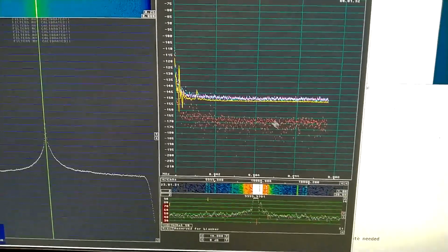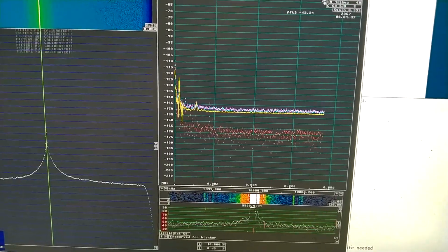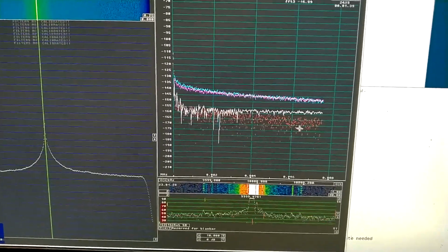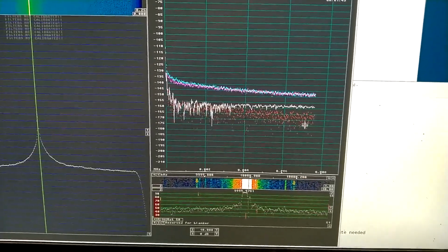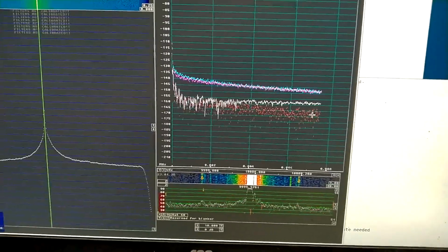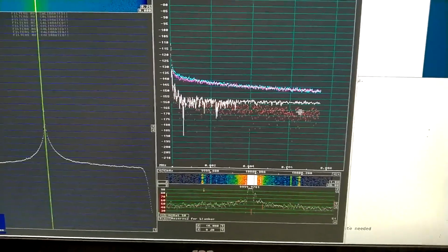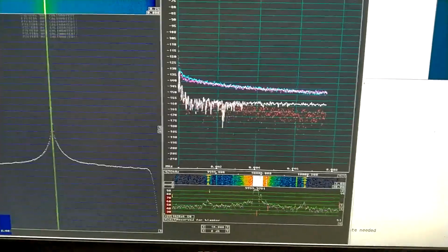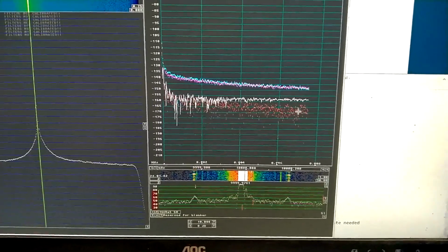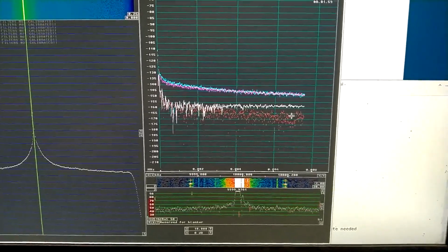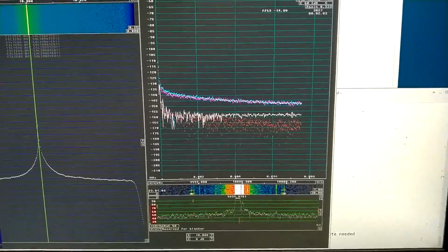The imaginary part is well below the real part. But for amplitude noise, the signal to noise level is not good enough. The imaginary part reflects the statistic noise, and below 2 kHz I don't have a reliable reading. And here at 7 kHz I would have to wait some more time to get a flat trace.